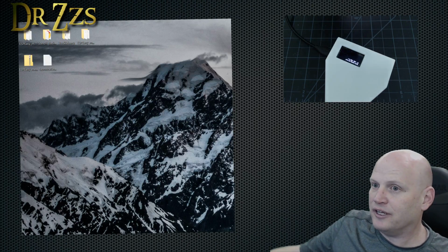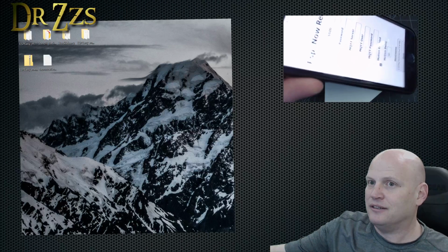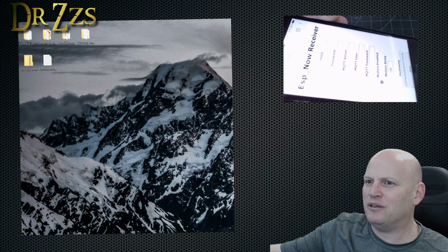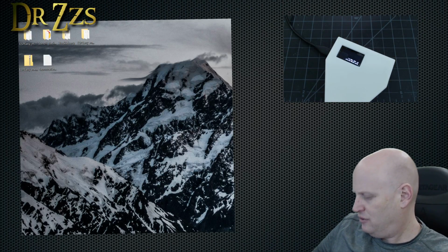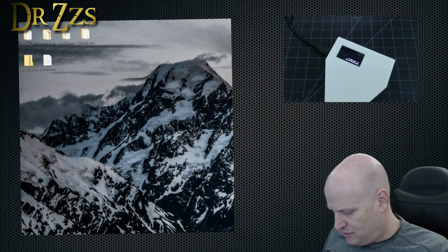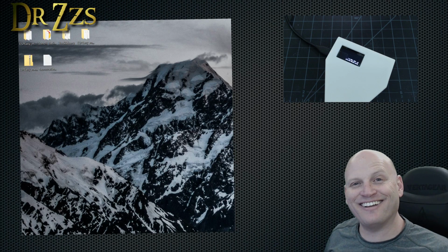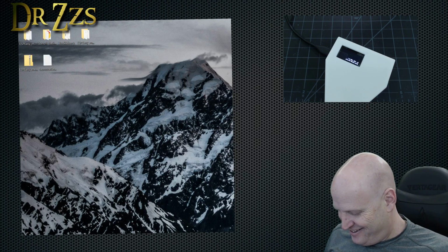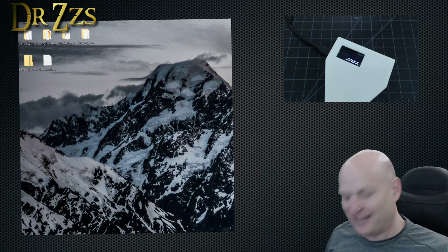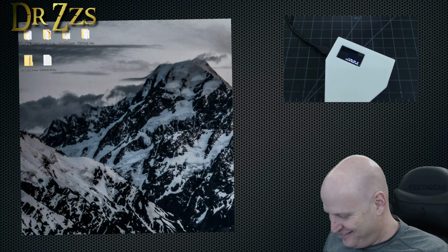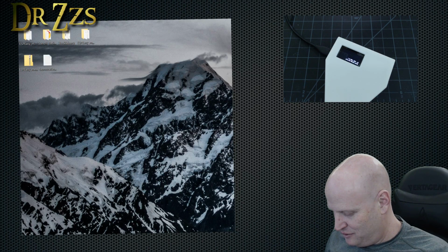Okay, I guess I should have done this on something you guys could see, but here's my ESP-NOW landing page, AP mode landing page. Now we're going to put in my Wi-Fi information here. You guys already know my Wi-Fi password probably, right? If you don't know it yet, just hang around. I'll probably reveal it at some point before we're done tonight. All right, I'm going to put my MQTT server in.